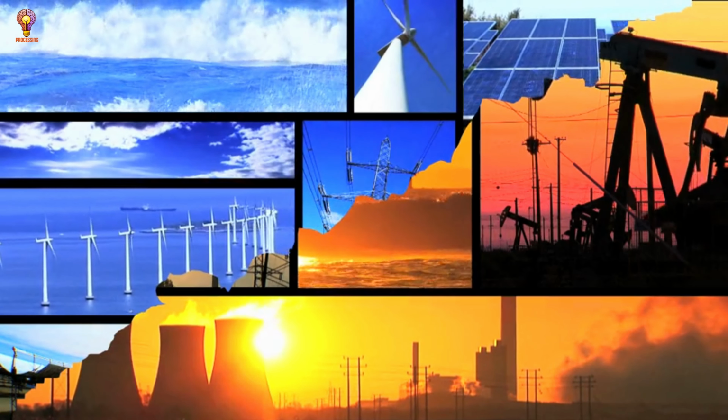3. Hydroelectric power plants. These plants harness the energy of moving water to generate electricity. Detailed steps. Water storage and flow control. Water is stored in a reservoir behind a dam. Flow is controlled using penstocks, large pipes.